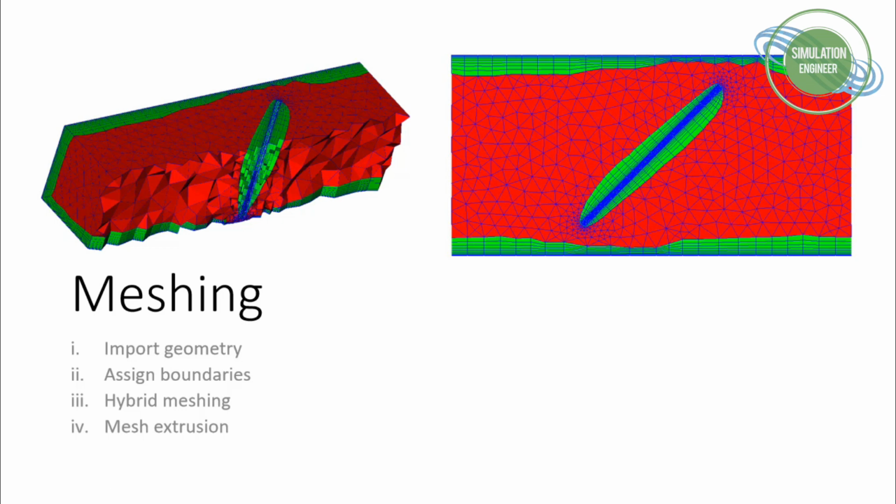Later on, I will also show you we will be extending upstream and downstream of the damper, with some extensions in both directions, in order to really have a fully developed flow. And after the damper, so after downstream of this damper, there will be flow separation, which we will observe later on. So really to avoid any kind of undeveloped flow or any other artifacts.